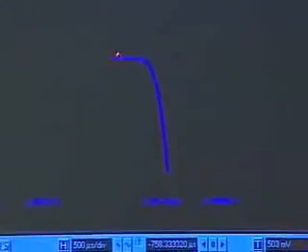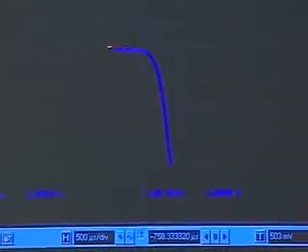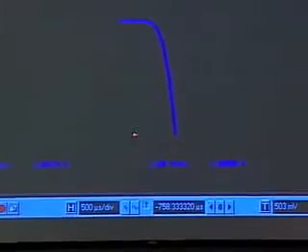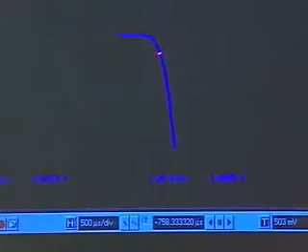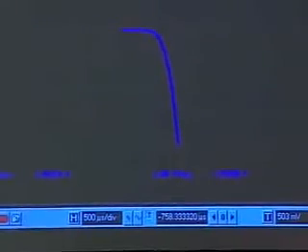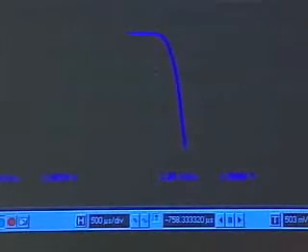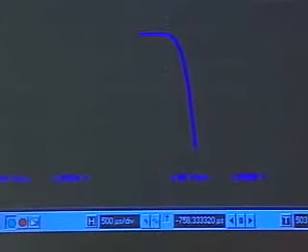So notice that here, that's the same curve, the transfer function, and the MOSFET amplifier output is at Vs until the input reaches the threshold voltage Vt. And once the input goes beyond Vt, the output begins to drop precipitously. And at some point here, this begins to go into its triode region.